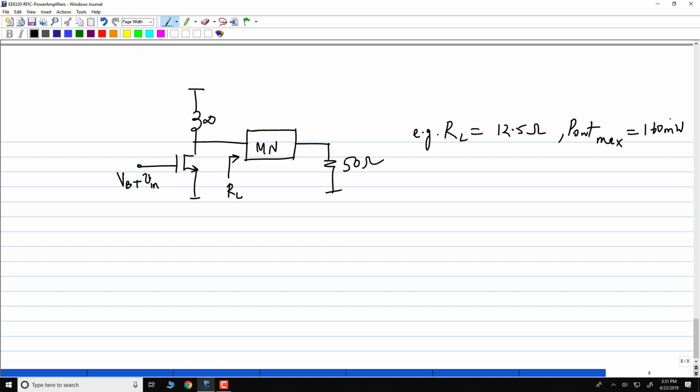I hope you realize that. If you really take an infinite inductor and build the circuit, it will act as a current source. Signal current will flow into RL, all the way down from extremely low frequencies all the way up to some RF frequencies. The primary limitation is in the drain bulk capacitance of the transistor. The same thing will happen. There is an RC bandwidth again in this case.